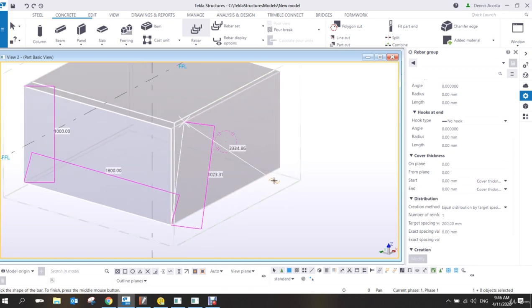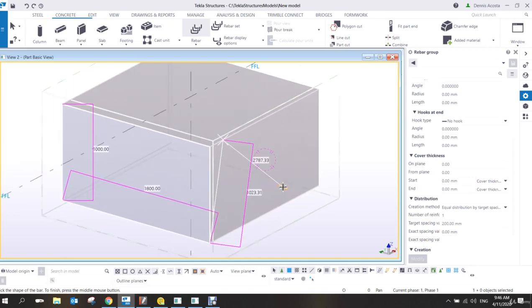Okay, so look, if you accidentally pick the wrong position, what shall we do? Escape, right click, interrupt. No need for you to go back from scratch, you press backspace. If you press backspace, look what will happen. You can now go back to the correct one. Only one backspace. It depends on how many mistakes you picked; if you click many points wrongly, press backspace accordingly.